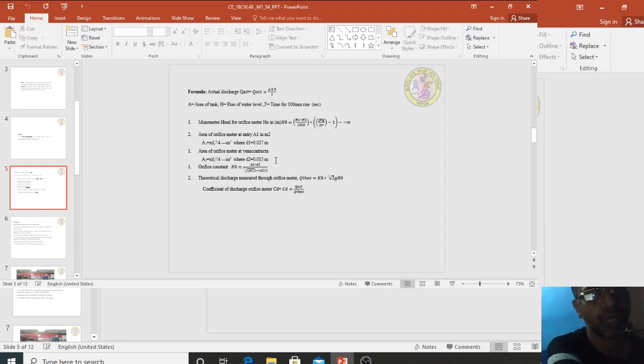meter. So I wanted to give an example here. Assume that this pen is a water pipe. There is a slope in this pipe, there is a contraction in this pipe. Let us forget about the entire length of this pen, consider this length. The area of cross section at this point is A1, whereas at the vena contracta, that is the tapered end portion, the diameter is D2.